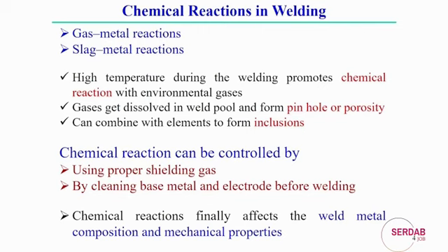Broadly, if you look overall at all types of welding processes, we can use a gas, basically shielding gas, to protect the molten pool. Therefore, we need to know the interaction between the gas and the molten pool, or when the molten pool becomes solidified, what reaction happens between these two components. This is one way. Another way to protect the molten pool is by using some slag.